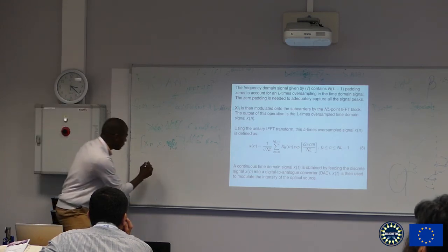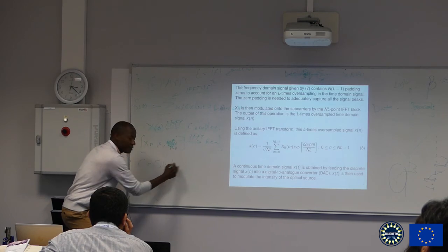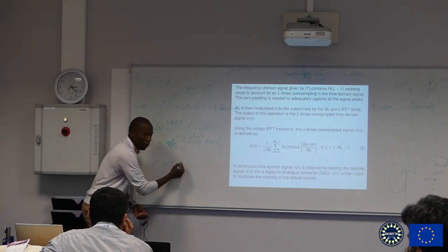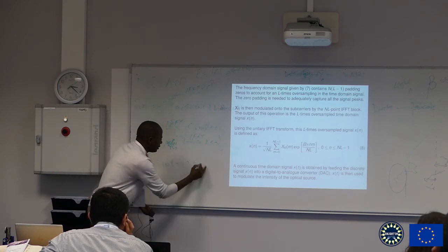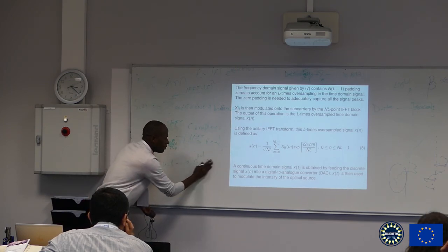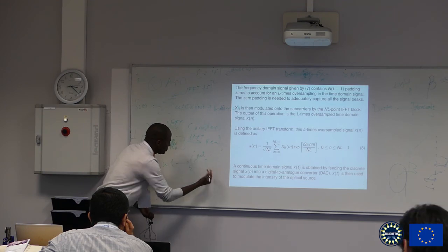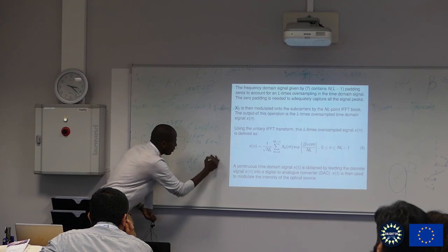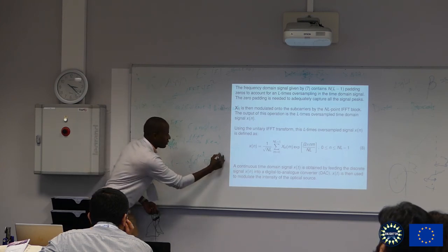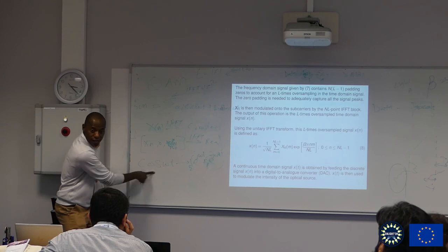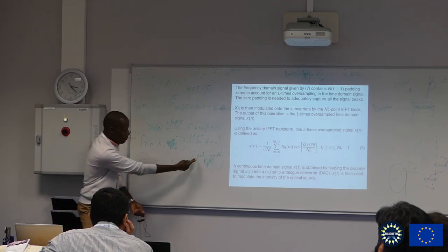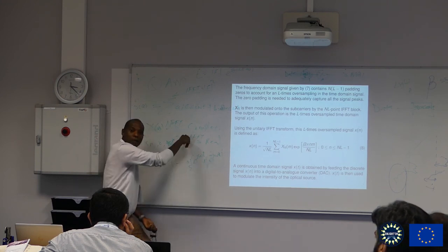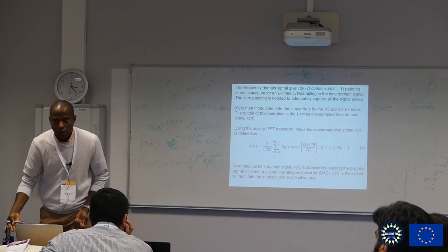Just like this. If you have cosine of omega_c t, and you break this into its Fourier transform, or in exponential form, this becomes one half of e^(j omega t) plus one half of e^(-j omega t), correct? That's true, right? But what is the frequency here? It's just one omega. But I have both the positive part and the negative part. So that's what we replicate with Hermitian symmetry. You get the point? Exactly.